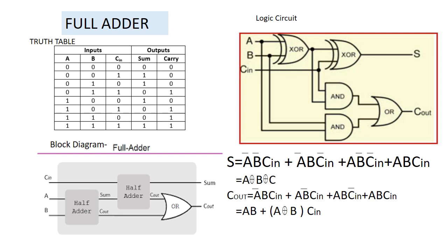The full adder. A full adder is a combinational circuit that adds two bits and a carry and outputs a sum bit and a carry bit. When we want to add two binary numbers, each having two or more bits, the LSBs can be added by using a half adder. The carry resulting from the addition of the LSBs is carried over to the next significant column and added to the two bits in that column.